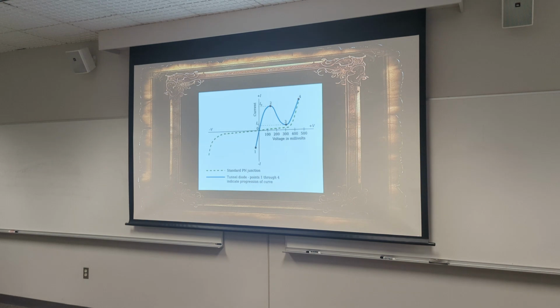So as we see, with just a little voltage before the activation voltage, we get a spike in current and then a decrease, and then it increases steadily from there after the activation. And as I said, these are very good for high-speed switching operations.